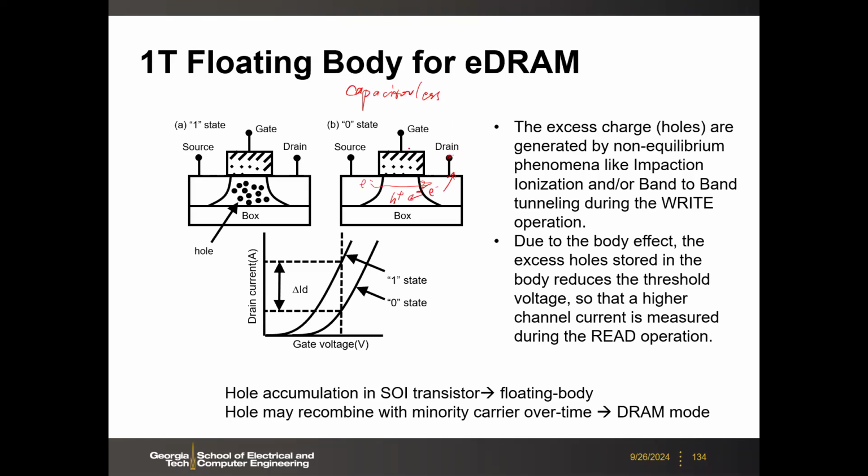But for this SOI technology, there's no body, right? This is insulator. So the holes do not have a body to go to. Therefore, the holes will be accumulated in the channel. This will raise the potential of the channel, and then you get higher drain currents. So that's one state.